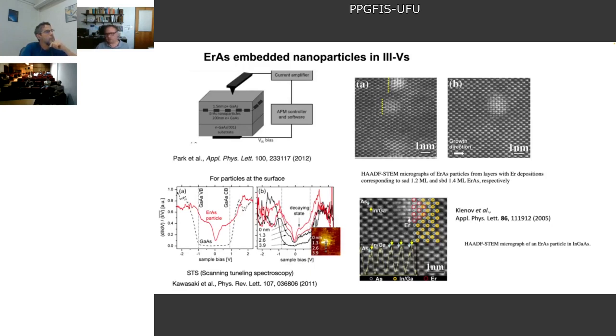And one of the things that caught attention at that time was perhaps that could be a good thermoelectric material, because the particles could scatter phonons, but you still have a high conductivity due to having a 3-5 matrix like gallium arsenide with high mobility electrons. And then the ZT would be very high, right? That was partially true, but actually didn't happen. But they can controllably do this growth, right? You have to be careful, because we are looking along the 110 direction here, and I'm going to show some of the details.